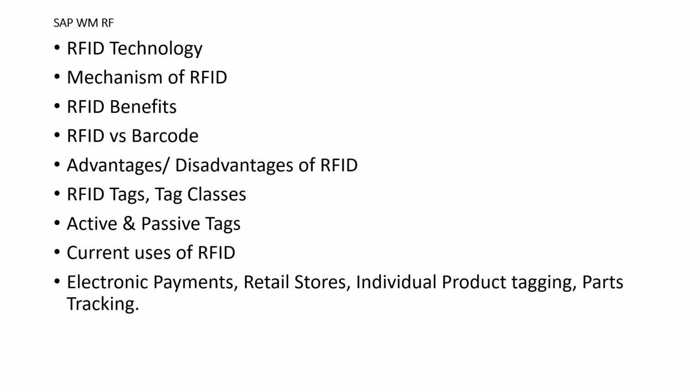RFID tags are essentially microchips that act as transponders, always listening for the radio frequency signal sent by RFID readers. When a transponder receives a certain radio query, it responds by transmitting its unique ID code back to the transceiver. Most RFID tags do not have batteries. Instead, they are powered by the radio signal requesting a reply.